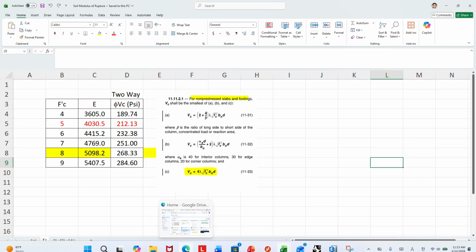Concrete. So why the shear? Because I think in your concrete beam design, you already learned that the shear force is going to develop a diagonal tension, right? So we usually add the shear stirrups in the beam, right? But somehow here, the question is, this is a mat, it's two-way. What kind of shear reinforcement arrangement do we have to apply?